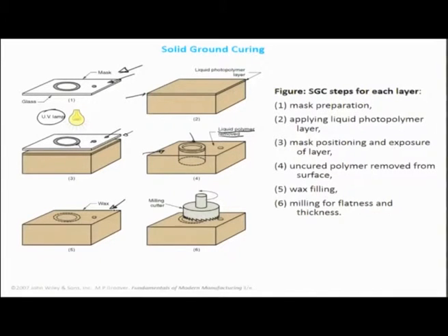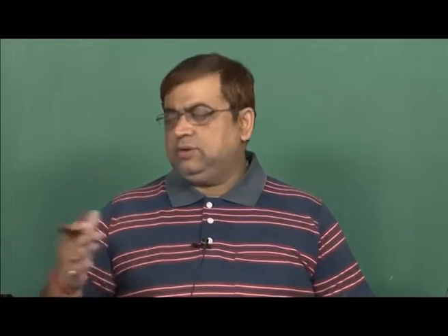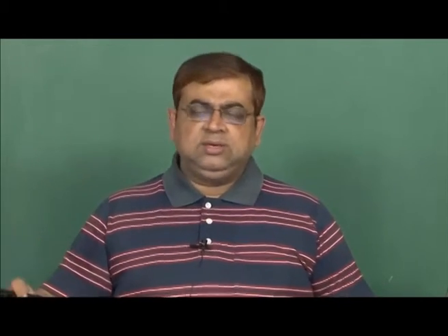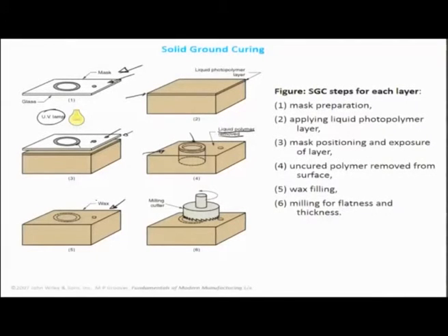Okay, so you can say that this is also sort of equivalent to the lost wax method, particularly in investment casting, where you create a feature or a shape in wax, and later on that acts as a core, and you can have metal flow over it, and you can retain the wax out so that there is a cavity which exists. Okay, so in the same manner, in this particular case, we can couple this as a process between the lithography and the lost wax method.